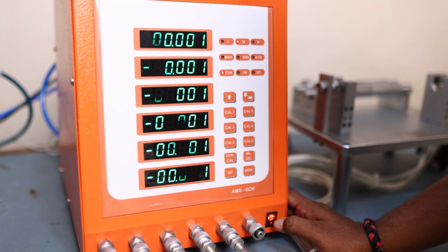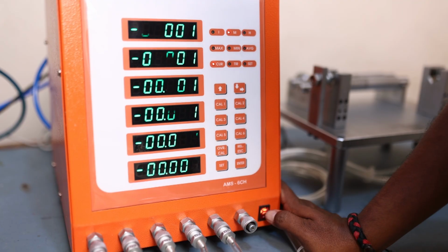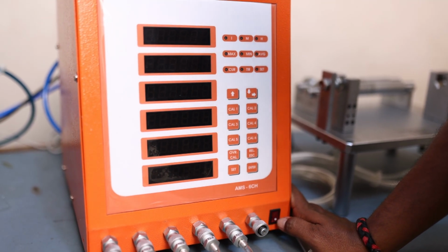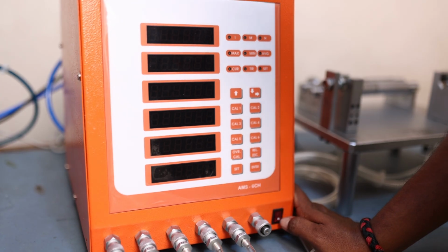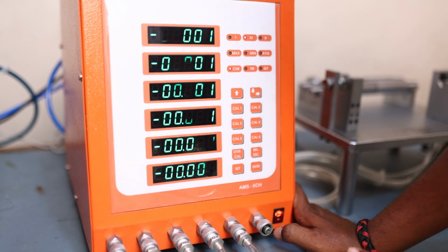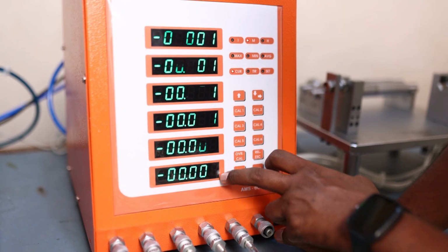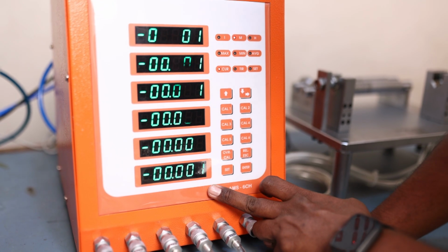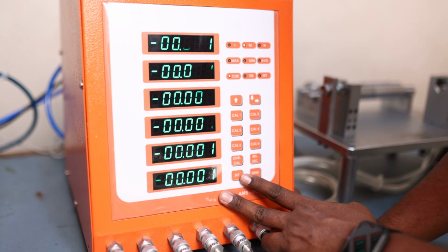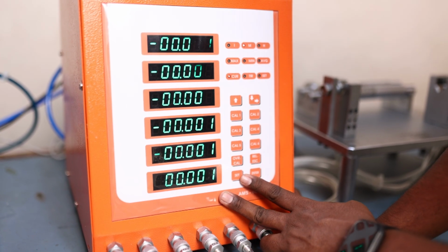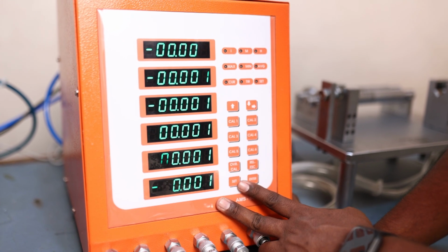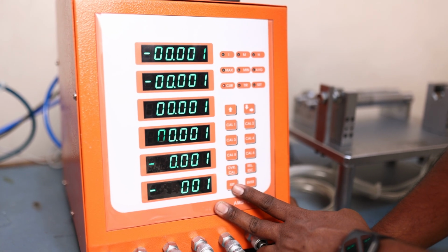To store the data you have to switch off the unit and switch on the unit after 2 to 3 seconds. Once you switch off and switch on, the display looks like this. Now let us start to enter the values of mean, USL, LSL, higher master value, lower master value and ovality value of the fixture or the gauge that you have to measure.